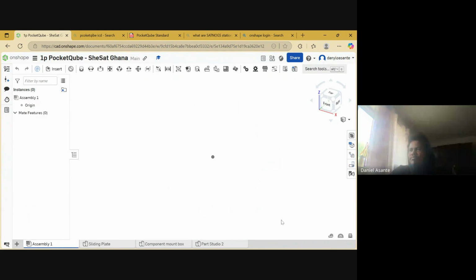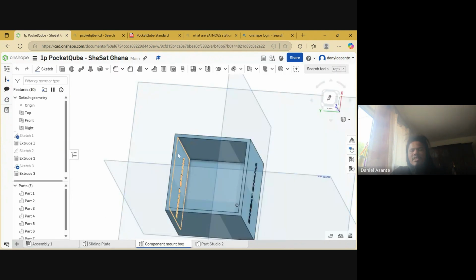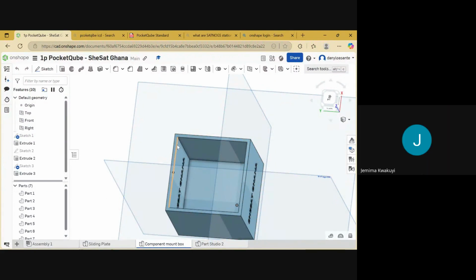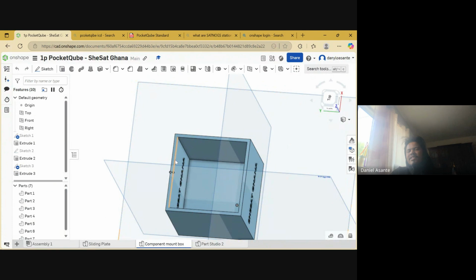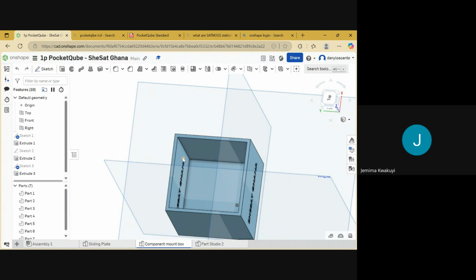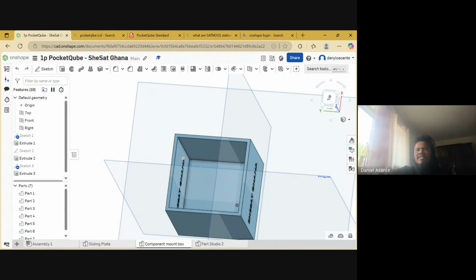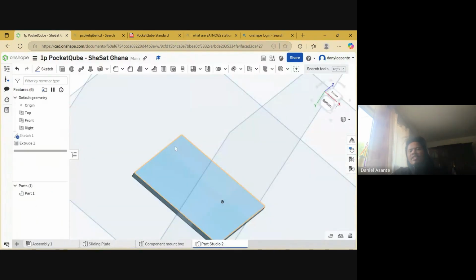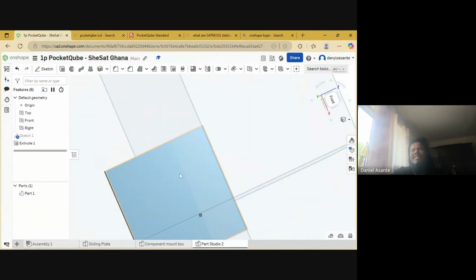the error margin. I was saying that since the cover we are making is the size of 46 millimeters, we want to size it to fit within 46 millimeters, and it shouldn't be too big or too small. So I have chosen to make my dimension 45.6, right?